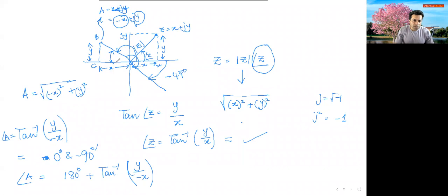If you don't want to use negative x and y, if you just want to use length, that's perfectly fine. You can just do tangent inverse of y over x, whatever the length is, without going into the negative and j or whatever. And then it's going to give you this angle. So this will be the angle right here. Once again, this is not the angle associated with this point in the complex plane. You still have to find the angle. This whole thing again is 180 degrees, from positive x-axis to negative x-axis, so you have to subtract this to find the rest of the angle. So in this case, you are going to do 180 degrees minus tangent inverse of y over x, and that will give you the correct angle.